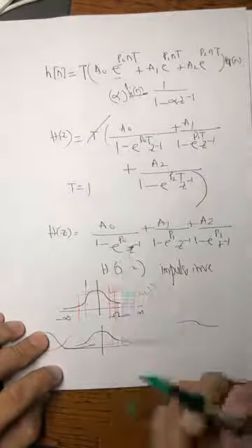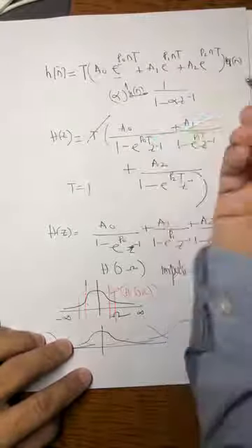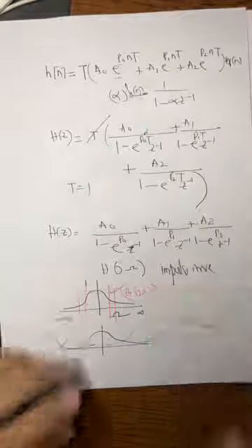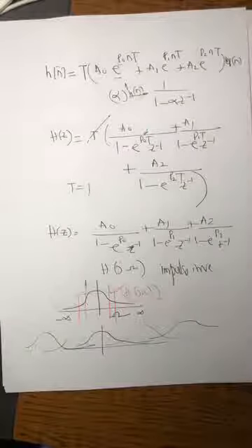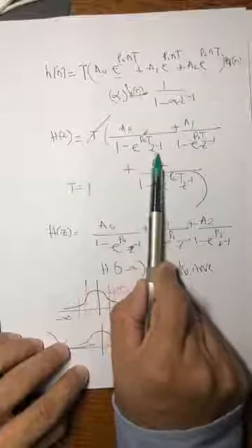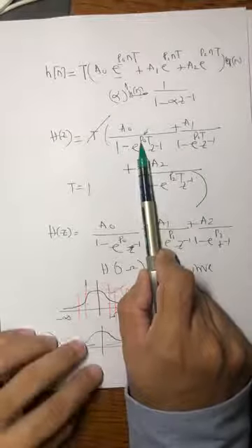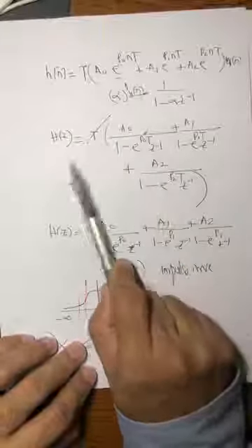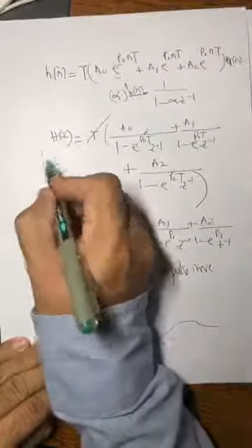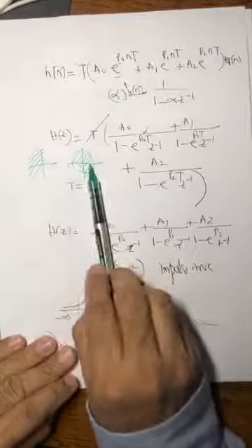And this tells us something very simple. Again, you don't have to go through the whole process. All you need to know, and remember, you can keep T equal to 1. So the pole comes right from where you have actually calculated the pole, on e to the power p naught z inverse. Because if it is on the left hand side, the exponential of a negative is always less than 1. So this transformation guarantees that a pole on the left hand side will map, so the left hand side of the S plane is mapped in the z domain inside the unit circle. So a stable system here will result in a stable system here.